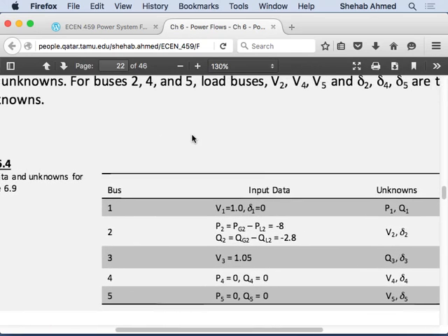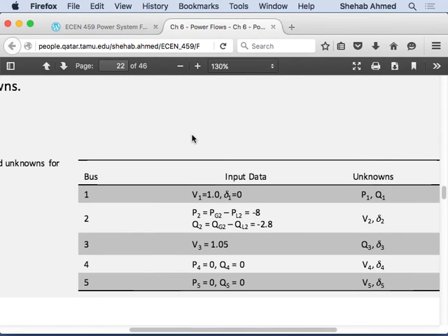that for a slack bus, we generally will start with 1 and 0, okay? But this is not necessarily the case all the time. Let's say you have a loaded system, and in PowerWorld sometimes it will not converge. Have you tried that? Try building a small system or pull up one of the examples and increase the loads. If there's a limit, remove the limit and keep increasing the loads. It will tell you it will not converge.